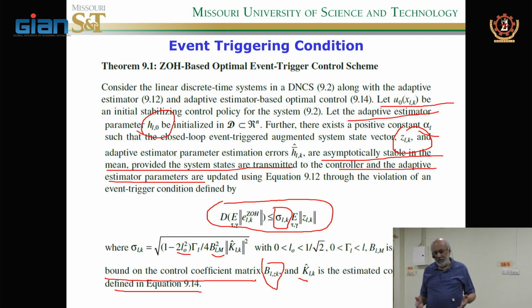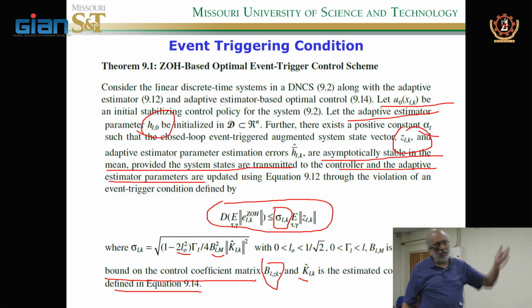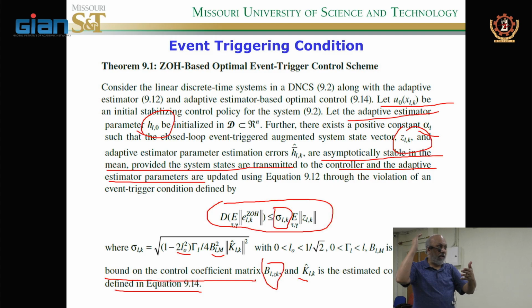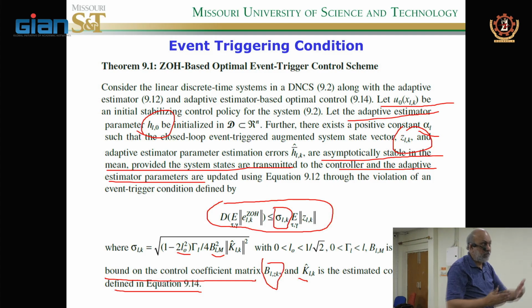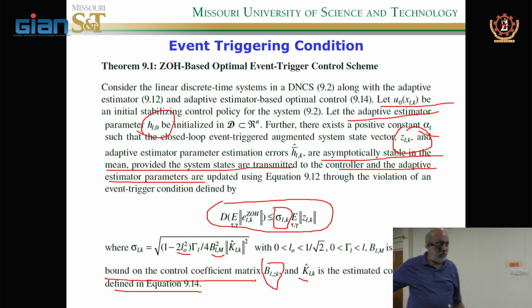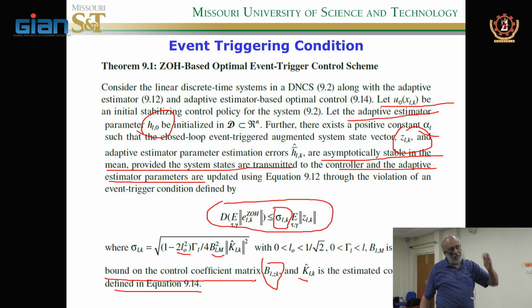Then we said, even then you are constantly transmitting, because every controller uses periodic sampling. Whether you like it or not, you are sending at every sampling instant the state vector and the control input. Remember that. So how do I reduce it without making the system unstable? Then I have to go for event-triggered control. Event-triggered control has another switch. Based on the performance, you decide, do I need to transmit even that minimum data?